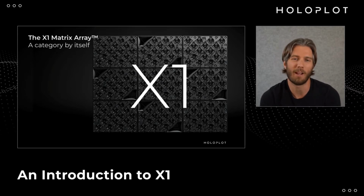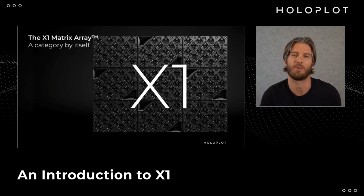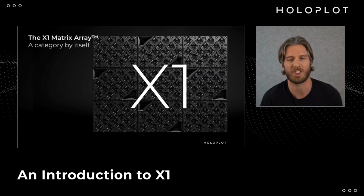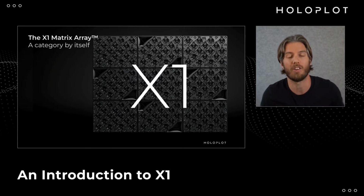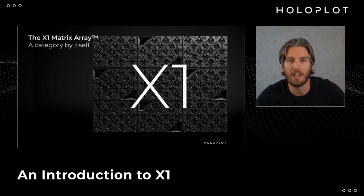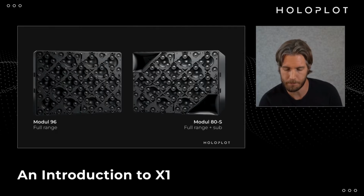And when we build these matrix arrays, we're able to build the matrix out in both the horizontal and the vertical. A lot of the time we do that to match the aspect ratio of the room. Or if you have very reflective side walls, for instance, but quite an absorptive rear wall, and you want to take all the energy off those side walls, then you would build the array out wider to get a greater level of control in the horizontal plane, to focus the sound where you want it and not on the reflective surfaces where you don't want it. But we'll look at that in a little more detail coming up.